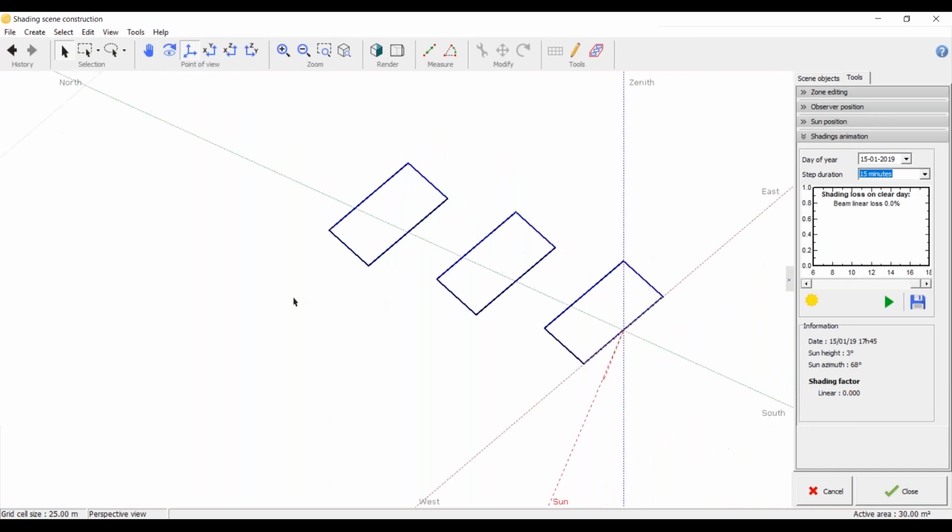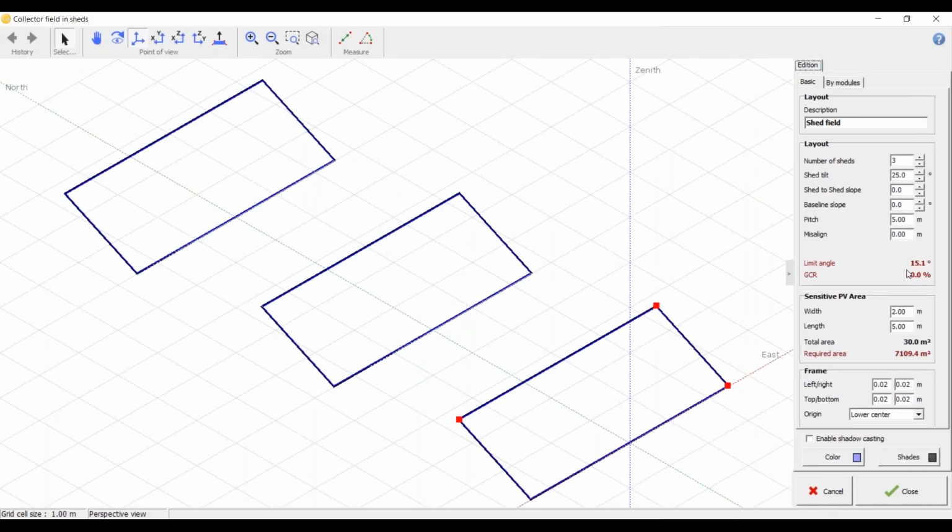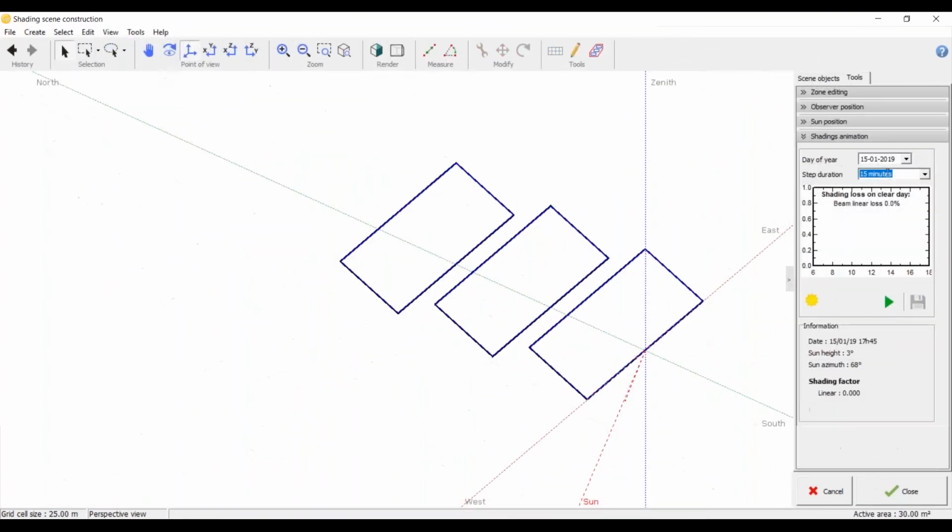So this is how I would run it. Hold on one second. I'm going to keep it a bit closer so that you see some shading losses. Right. So instead of December 21st as the default date, you can move to the months that you want, and you can run a shading analysis, and then you can see what the shading losses are.